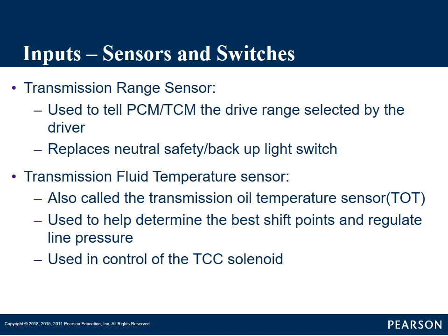Most of these are located on the valve body. A lot of times they're part of the pressure switch assembly, which we'll talk about here in a little bit. Sometimes they are a switch screwed into the side of the transmission. The line pressure runs on the back side of it, and it can determine the temperature of the transmission.